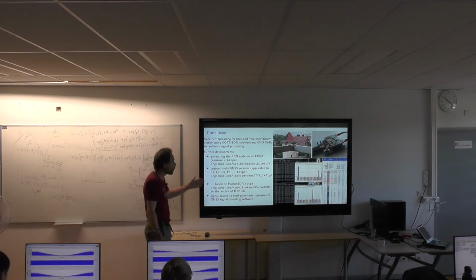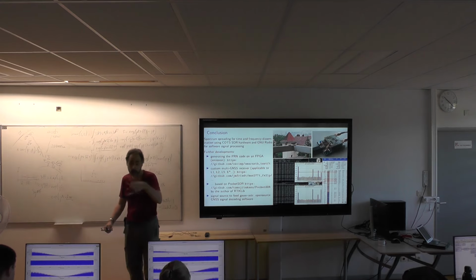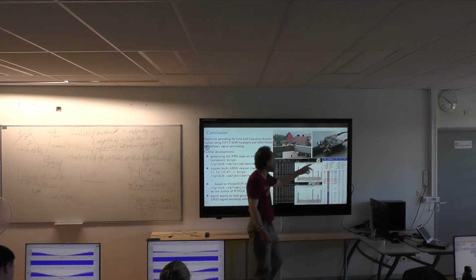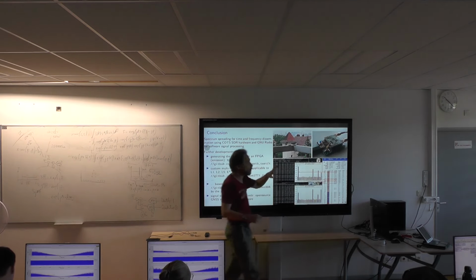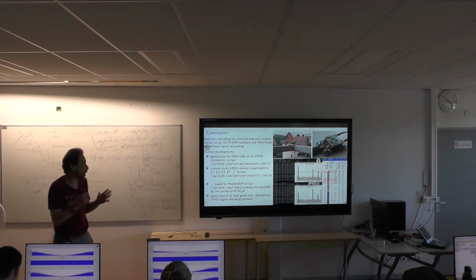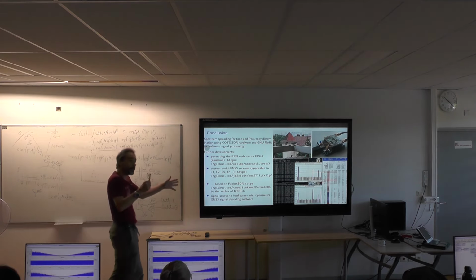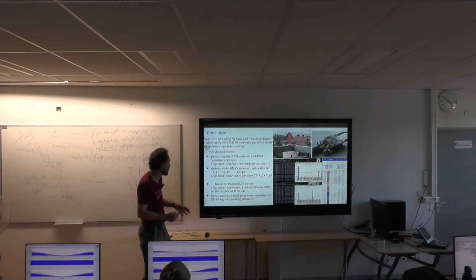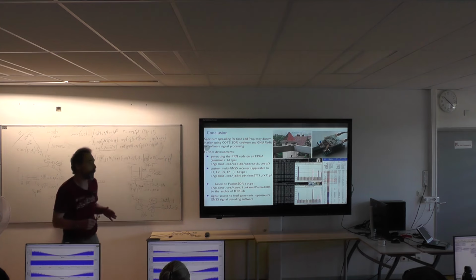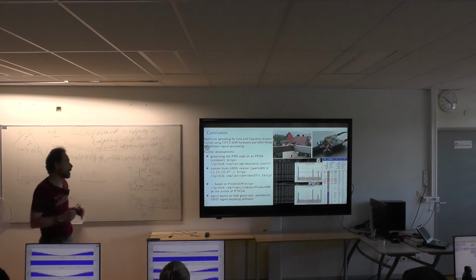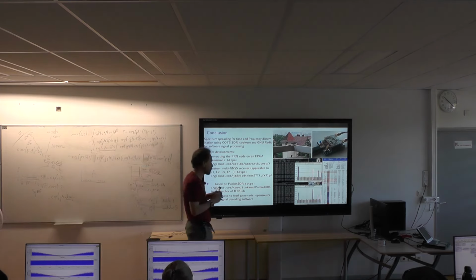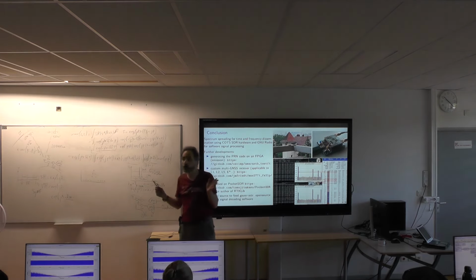You can have more fun with additional constellations that you can look at. There's awesome work by Tomoji Takasu, the author of RTKLIB, who developed the Pocket SDR with my master's students. I reassembled the Pocket SDR. It's 20 euros worth of hardware, and it gives you 40 megahertz, so you can access Galileo or L5. And if you want to do real-time processing and not post-processing as we did, you've got GNSS-SDR, which can be fed the software-defined radio output and process the GNSS in real time, depending on the computational power you have access to. And with this, I thank you for your attention.